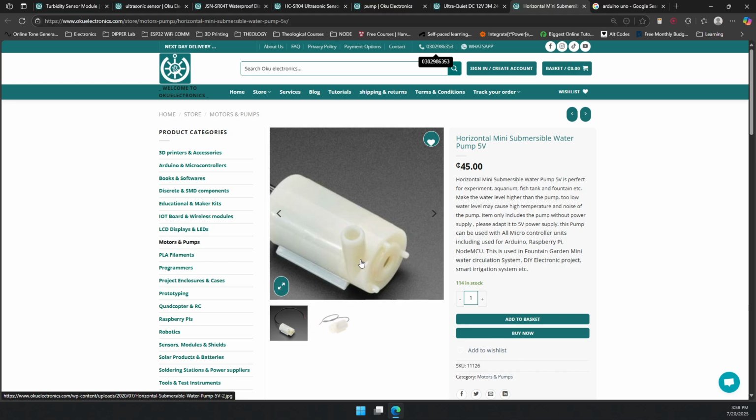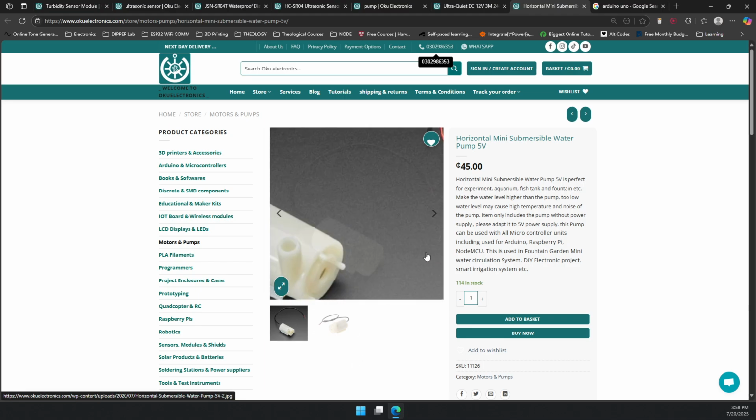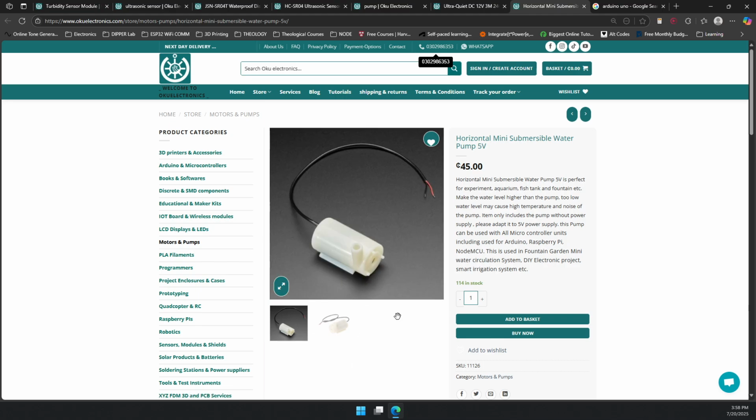The signal will be used for something else, but to power an actual device, the pump requires power. So to power an actual device, the digital pins on the Arduino will not be able to do that. The same is said for the ESP32. The pins on the ESP32 at best are for communication, sending signals, and maybe you can use them to turn LEDs on. LEDs don't require much power. But for a pump, it's a no-no.